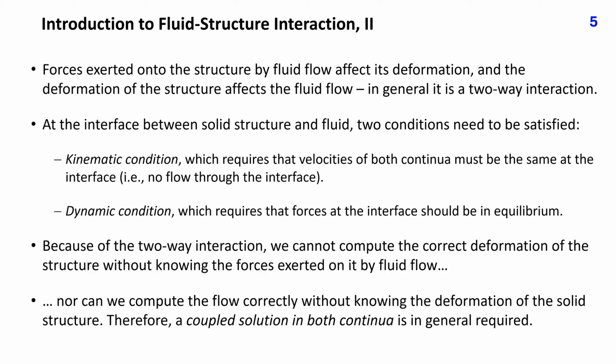Forces exerted onto the structure by fluid flow affect its deformation, and the deformation of the structure affects the fluid flow. In general, there is a two-way interaction between flow and structural deformation. At the interface between solid structure and fluid, two conditions need to be satisfied. Kinematic condition, which requires that the velocities of both continua must be the same at the interface, that is, no flow through the interface. And dynamic condition, which requires that forces at the interface should be in equilibrium.